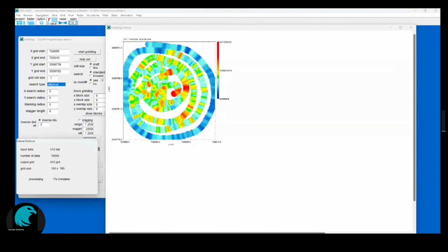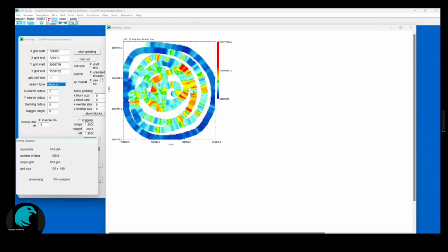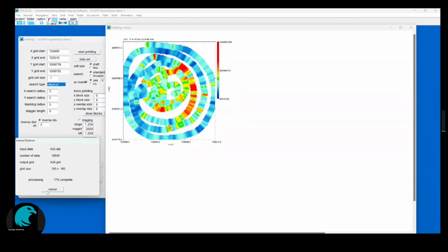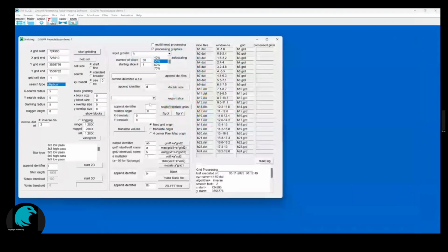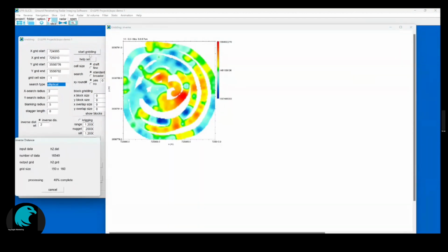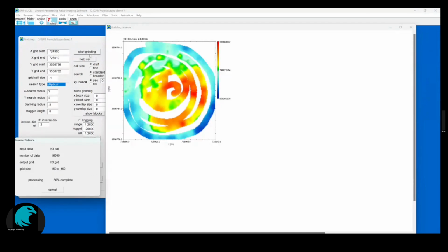And you notice that we're not actually interpolating past the lines, and it's not including data on nearby transects of the GPS profile. Now what you could do is, if you wanted to still see the tracks, but you want to interpolate further, we could actually set the search radius out. Let's just make it, for instance, 2. But I'm going to leave the blanking radius the same at 0.5 meter. And now we're searching out further, and we're interpolating across the line. So you can actually see features that are maybe more coherent by searching out, but still preserving what the track looks like.